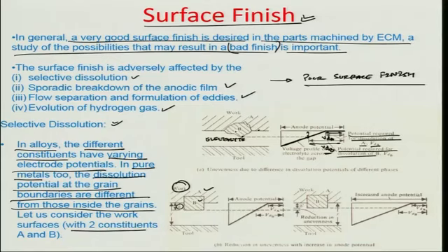Typically in a pure phase alloy, we estimated in all our calculations that this whole surface is equipotential, and the dissolution would happen, and the recession of the workpiece would happen as a flat surface. In this case it is no longer true, and so there is unevenness due to the difference in the dissolution potentials of the different phases.